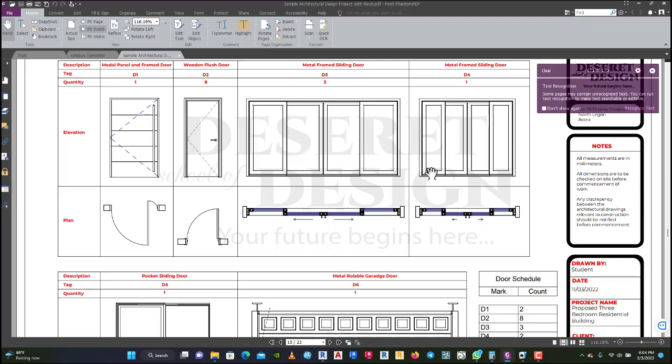Do you get it? Okay, now if you've used AutoCAD before, normally you have to redraw it again. You have to draw using lines. Say this is a door, so this is the space of the door. Windows all the same thing, but in Revit you are not drawing. You brought that family inside the project, so you just go and pick it and place. That's all, and just dimension it. Do you get it? Okay, then how do you do it?